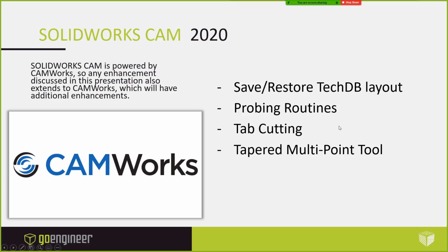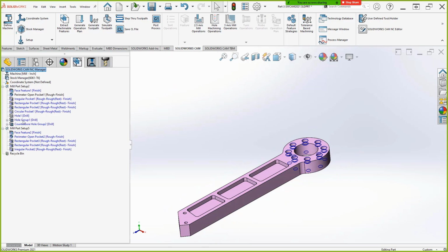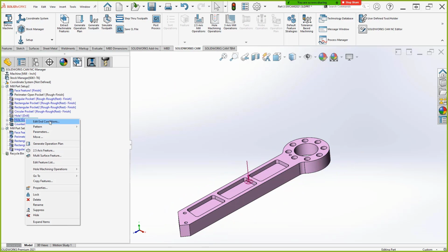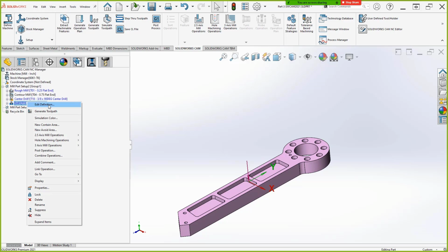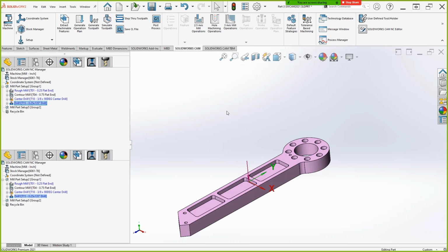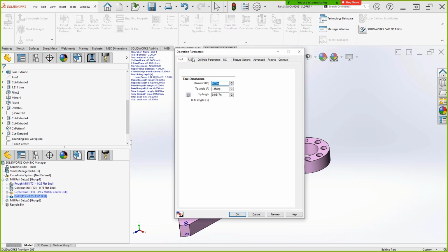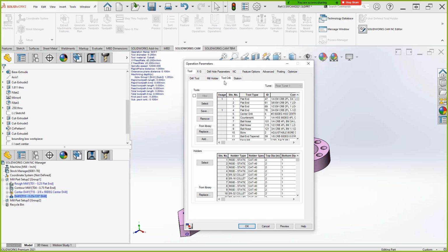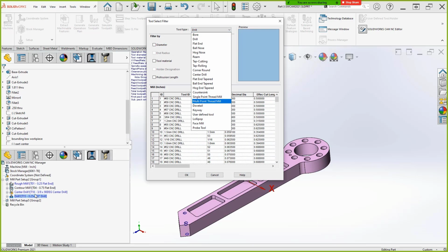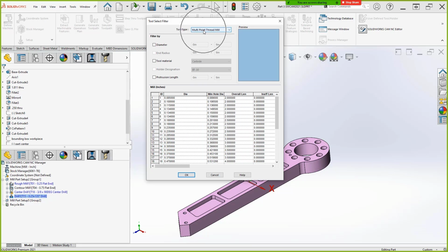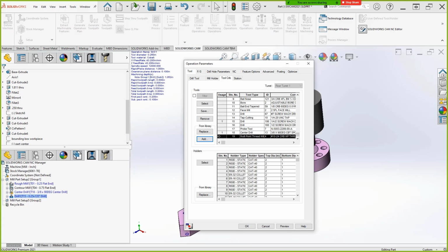All right. Tapered multi-point tool. This is just a nice addition to be able to use certain types of tools, to simulate those types of tools correctly within the software, make sure we're getting accurate results. So if we go look at this current tool on this drill operation, I'm going to go to my tool crib, add a tool, see if we can't find a... I know this is a drill operation. It's not a threading operation, but we're just trying to explore the fact that with a multi-point thread tool, if I choose one of those and select it...